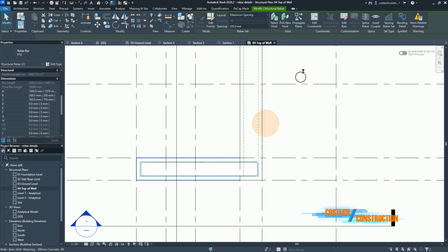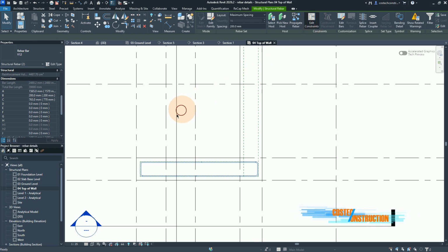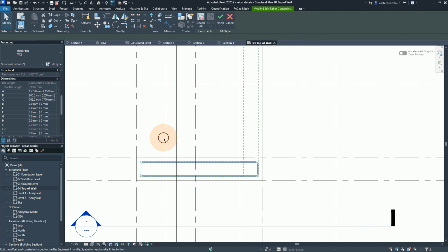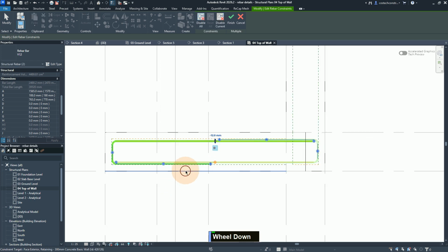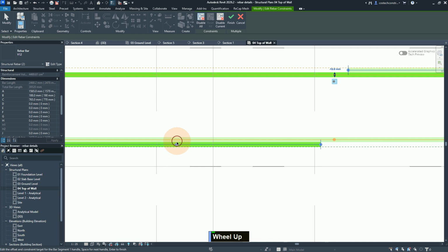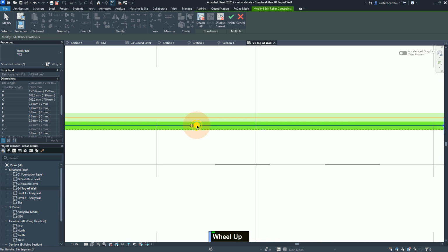Now with the two Rebar sets selected, we can go to Edit Constraints. And I can start by changing this one to -12. I'll pick at this one. I'll zoom, then select this other shape handle. Select this, then give a value of -12.